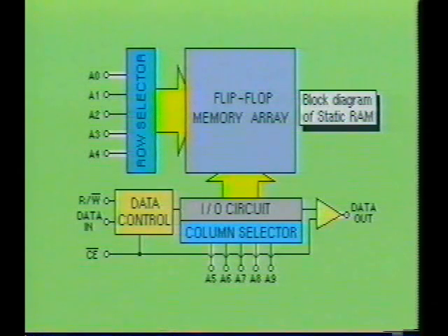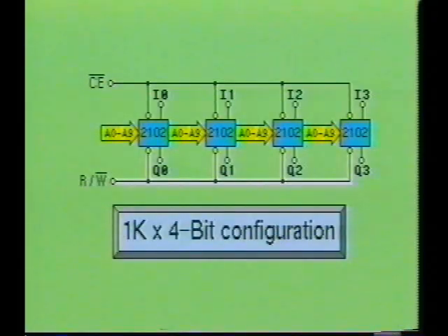As you may have noticed, there is only one data output on this device. By simply paralleling the memory ICs, you can create a 4-bit or higher output memory device. By connecting the address and control lines in parallel, the same address in all ICs will be selected simultaneously.